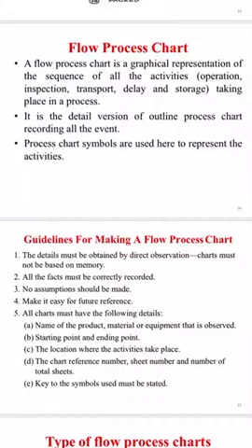If anyone asks you what is the basic difference between the operation process chart and the flow process chart, the basic difference is that in the first case we only record the activities related to operation and inspection, but in the second case we need to record all the activities: operation, transportation, inspection, then delay, then storage.